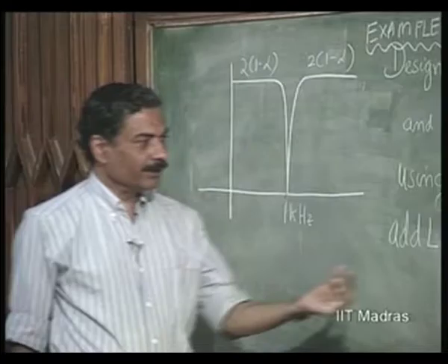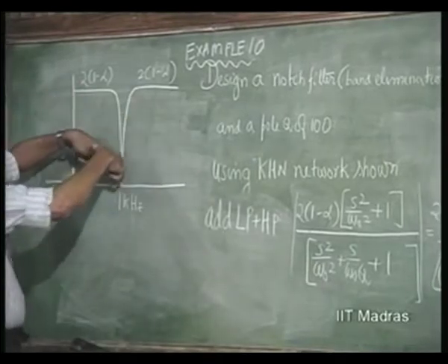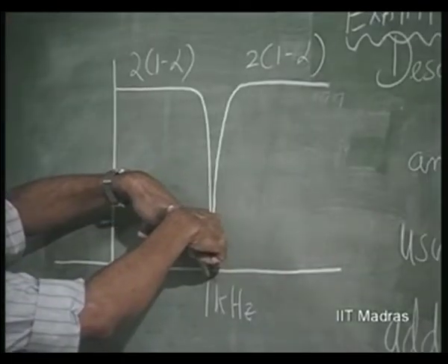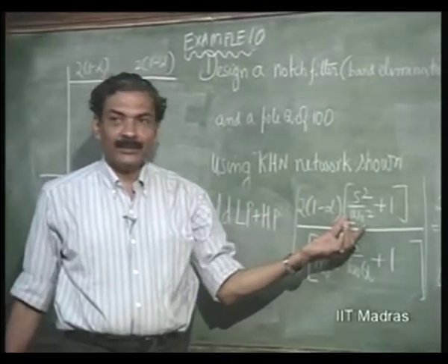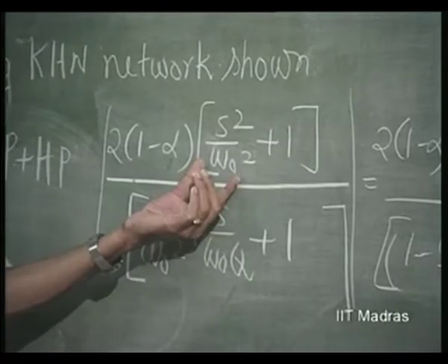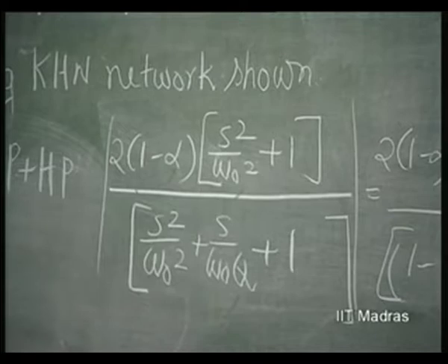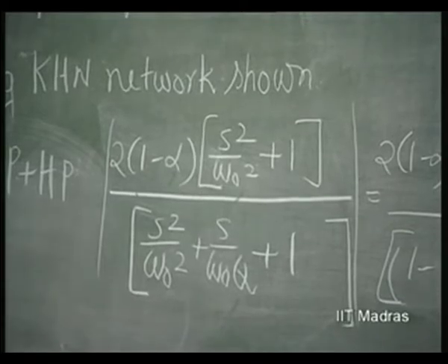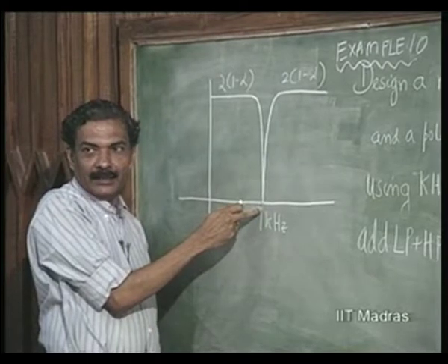The higher the q of the pole, the narrower is this pole. Okay? You can see that even this introduces simply a 0 at omega equal to omega naught, but the shaping of the 0 depends upon the peaking here, right. You are trying to make the pole give a peak here exactly at the point where there is a 0.